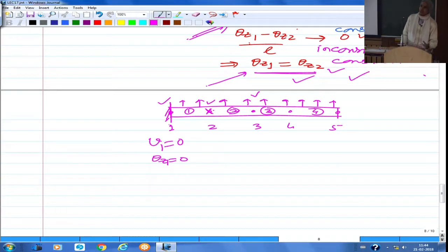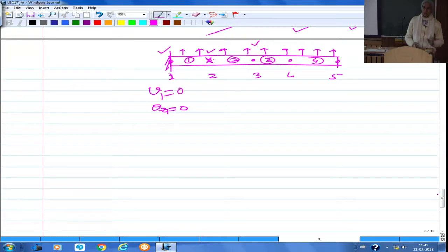What kind of effect is going to be there in your deflection prediction? This phenomenon of under prediction of deflection when you use Timoshenko or shear deformable finite elements for thin beam problems, where deflection gets under predicted, is the associated phenomenon we call shear locking.